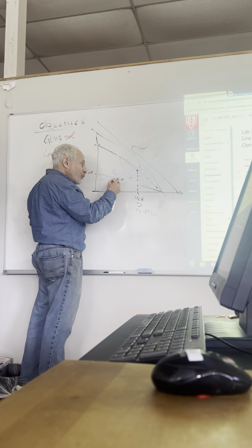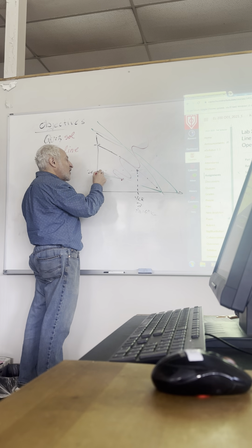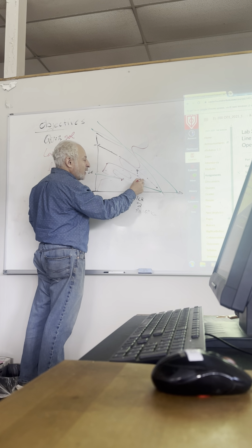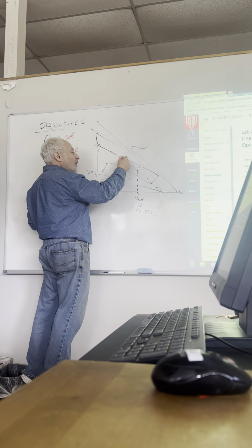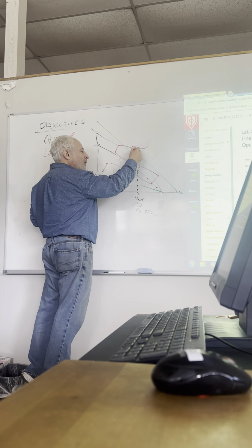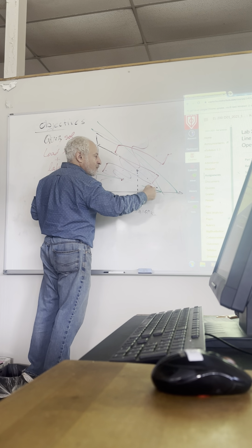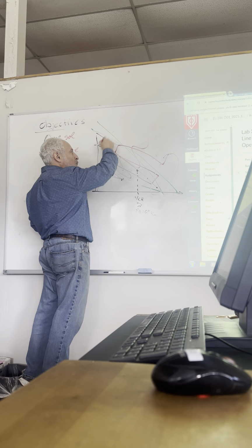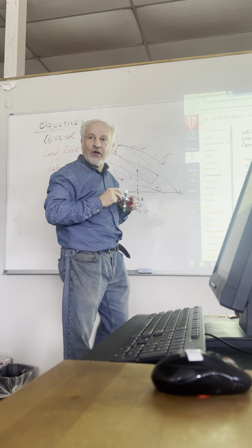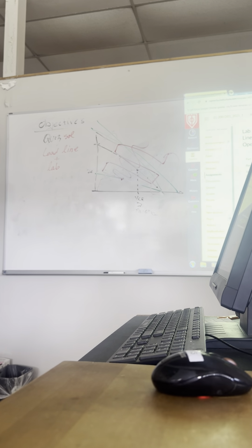Now, if your input signal is too big, by the time it gets here, we'll clip it, and by the time it gets here, it will clip. You will remember those clips you saw? Yeah, because we've reached cutoff and we reach what? Saturation. Hey, I could use that to create a square wave. Almost. Depends on the frequency. So you can reshape signals if you wanted to.